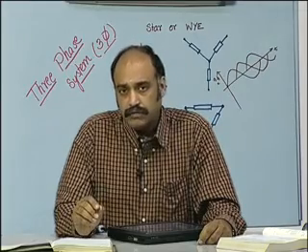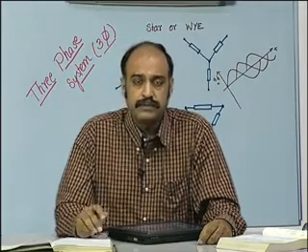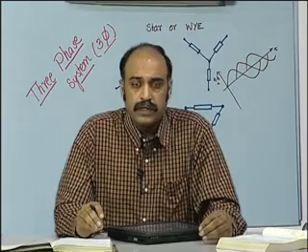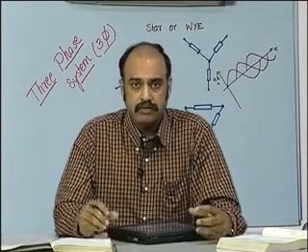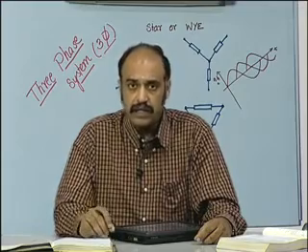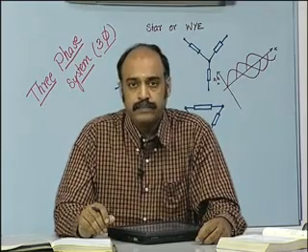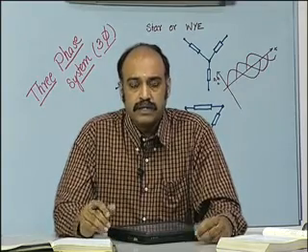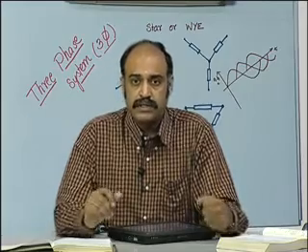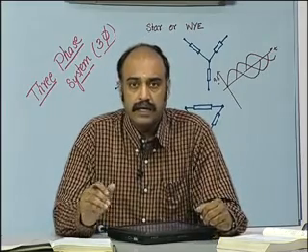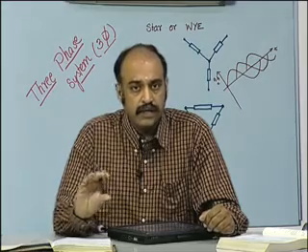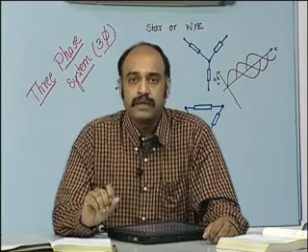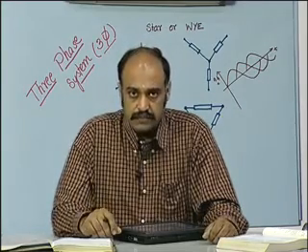Right in the beginning of the three phase circuits, we started with the star type of connection and then eliminated the neutral. That is, we started with a 6-wire system and then eliminated 2 wires, made 3 of the return paths common, and it became a 4-wire system.